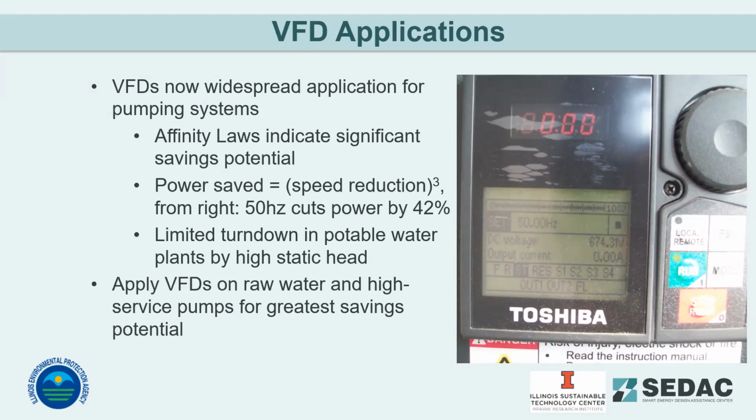It says 50 hertz equates to about 83% speed, so the power reduction is a decent amount. A lot of these things need to start up at 100%, and then you can back them down. We've done that with blowers in the past and saved quite a bit of money over time.